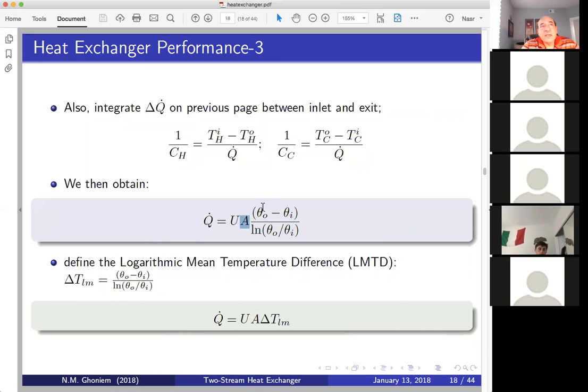And this form that comes here, you probably saw it in the heat transfer course, is called the logarithmic mean temperature difference, LMTD. So the end result is that Q dot would be equal to U times A times delta T Ln. And again, you notice here in this form of the energy transfer, the key is to finding this capital U that we discussed earlier.